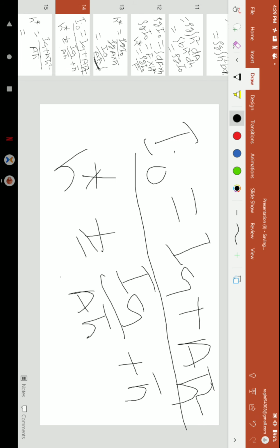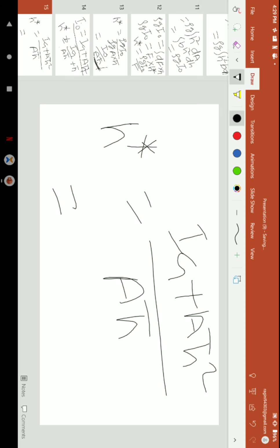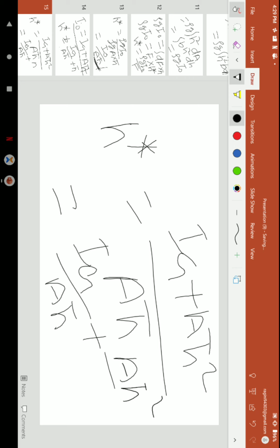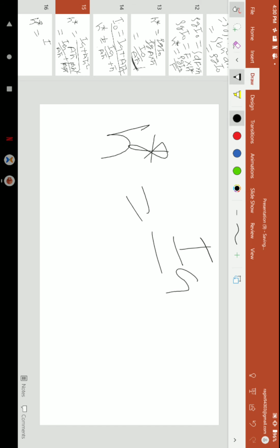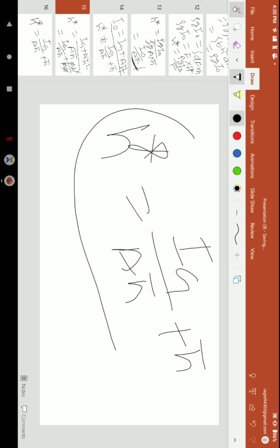We can write it like this: Ig divided by A h bar plus A h bar square divided by A h bar. Now what we are left with, h star is equal to Ig divided by A h bar plus h bar. This is the final center of pressure for the vertically submerged area.